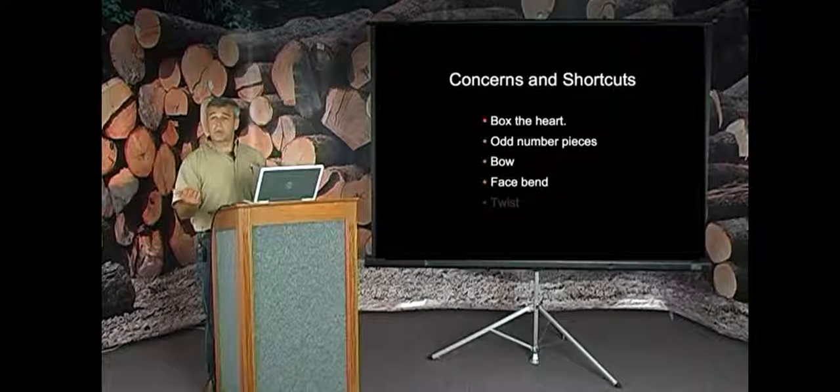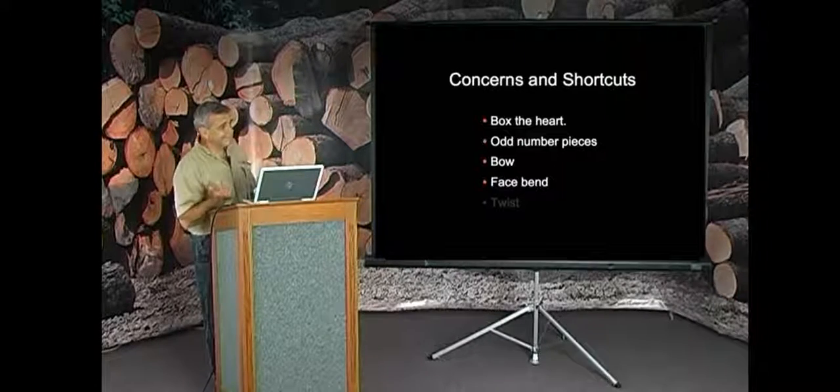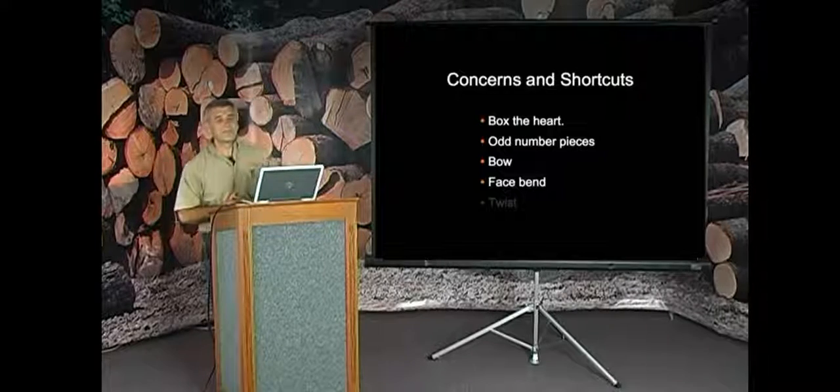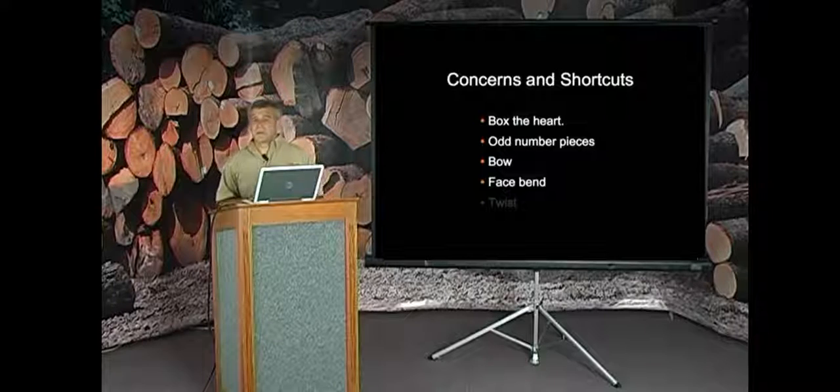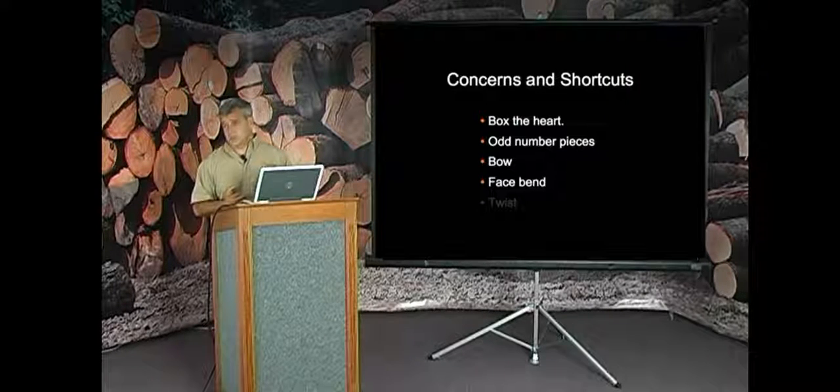Well, if you're cutting dimensional lumber, where are those defects the most undesirable? Bow, well, we were always told put a floor joist crown up. You almost expect a little bit of bow. A little bit of bow in a floor joist is fine. You crown it up. A little bit of bow in a roof rafter, that's fine. You crown it up. Start putting bow in a stud wall, and can you keep a straight wall with bow in a stud wall? Not if it's excessive at all. I mean, it needs to be kept very slight in a stud wall, bow.